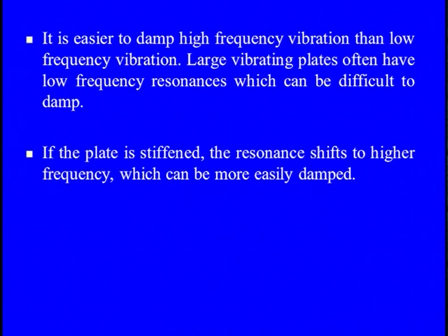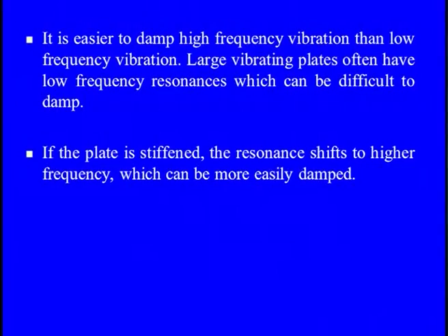Large vibrating plates. Certainly, when you have a large structure, the number of cycles during the oscillation is pretty low. So whenever we are trying to absorb the vibrations coming out from the large plates, they have low frequency resonances, and it's not easy to damp out those vibrations effectively in the way that we did in the previous case.